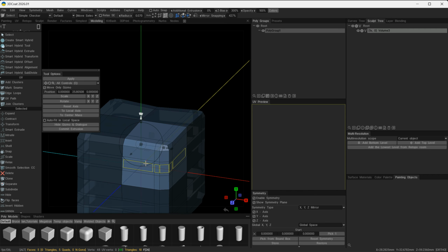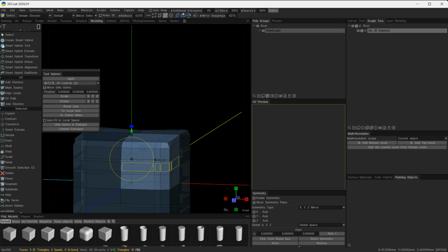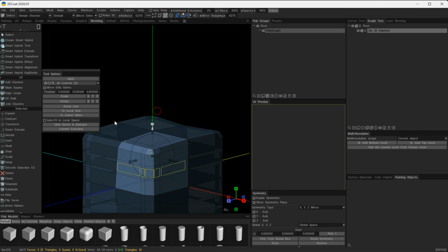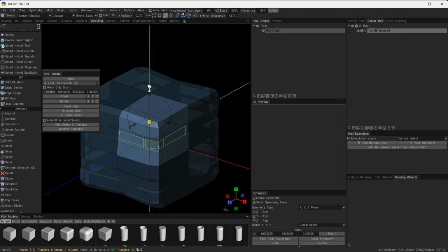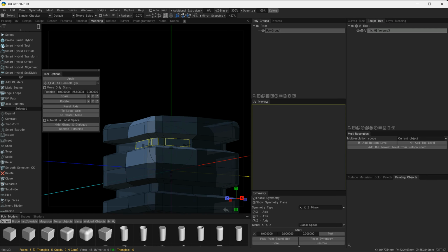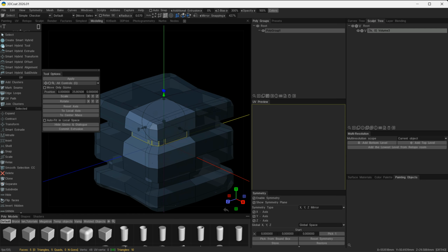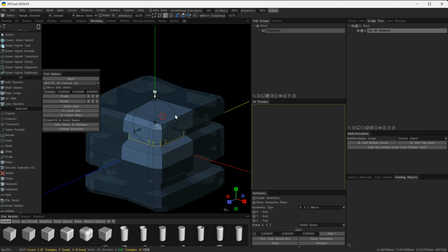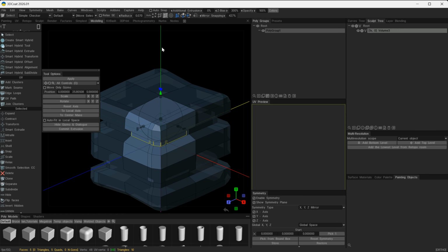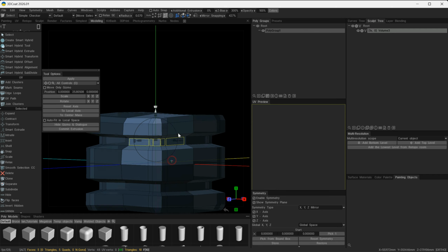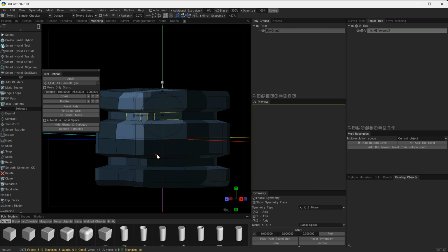At the moment it's got a height. The gizmo is sitting at a height of 25 on here, and you can see that now I'm able to use that extrusion and it's not giving me that error on the end. So it's important to understand where your axis is and to make sure that the gizmo, the rotation point or the scaling point in this case, is aligned with that axis, and then you won't have any issues.